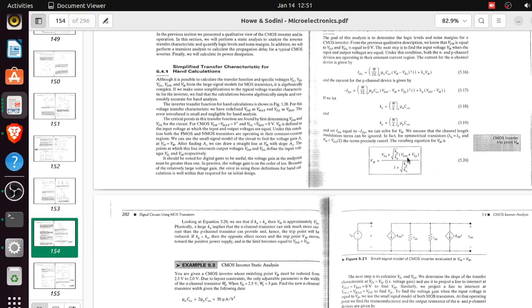We may not want that, because it means there is not enough room for the high abstraction. So you don't have so much room for the representation of the value 1. Maybe we can talk about this more mathematically, but I just want to give you guys insights. So that means the best option may be to make kp and kn equal.